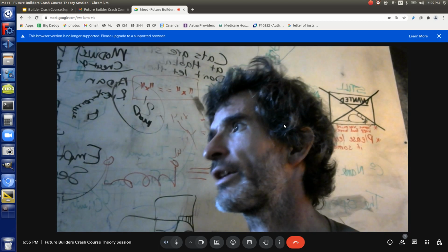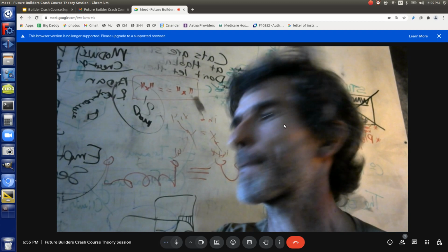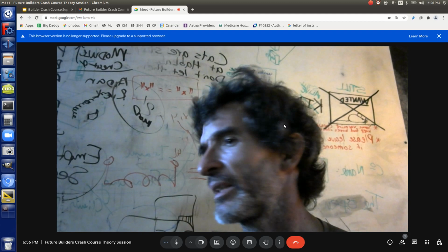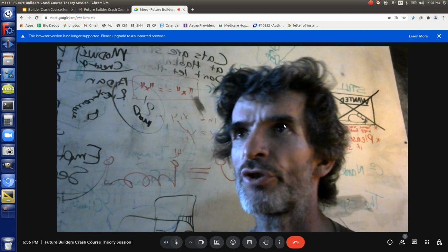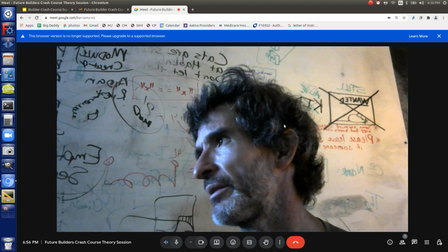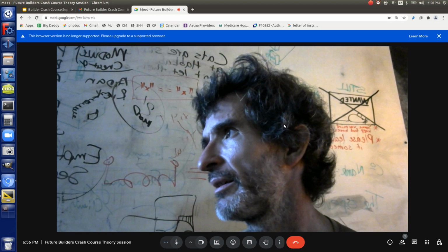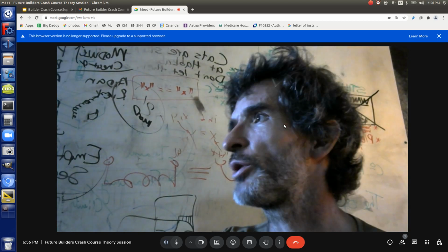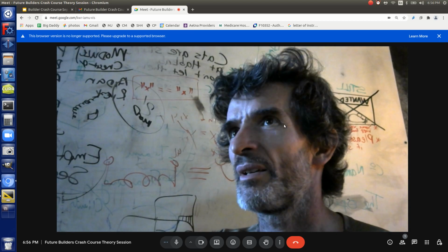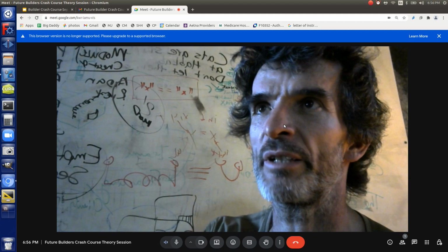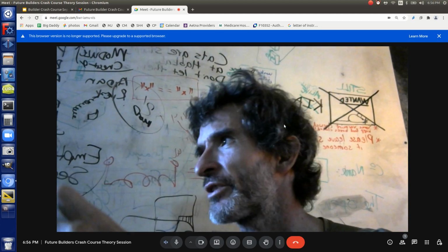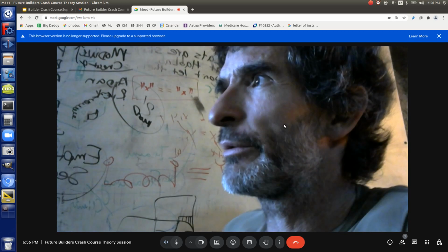So for example, if we're putting in, like each truss, we have each nail go through the OSB. We've got like a 20-foot truss. We put 40 nails into that OSB, into the 2x. How much are we holding there? Well, let's assume the limiting factor, it's close to the edge. We didn't even make that 2x factor from the say 1/2 inch OSB, that would be like 1 inch. No, if you're hitting a stud, you're only like 3/4 inch. So let's assume that the OSB will give first. So what's your limit there?